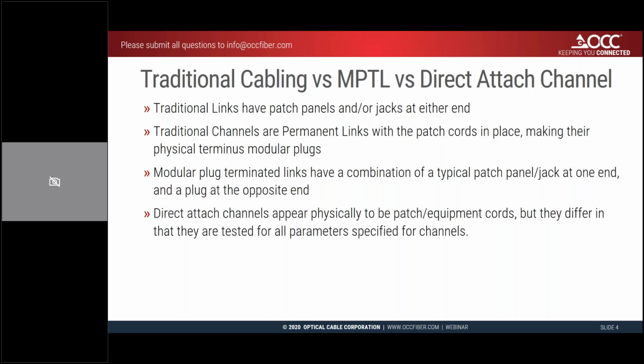So now a modular plug terminated link, that's kind of a combination of the two, and it actually has a patch panel or a jack, some sort of outlet at one end, and at the other end, it's terminated with a modular plug. Okay, and direct attached channels, a direct attached channel actually appears physically to be a patch cord. It's got plugs on both ends and no connectors between. But they do differ from patch cords in how they're tested, and we'll get into that a little bit as we go forward.